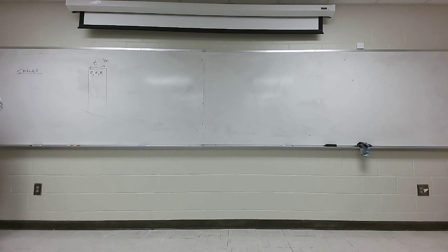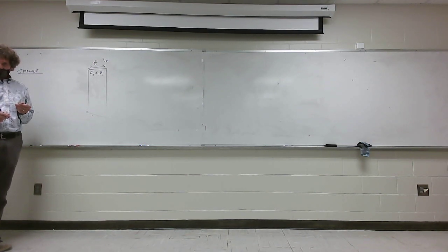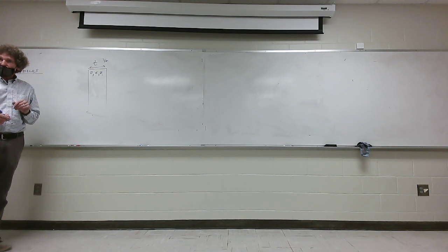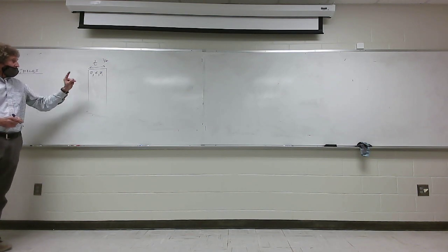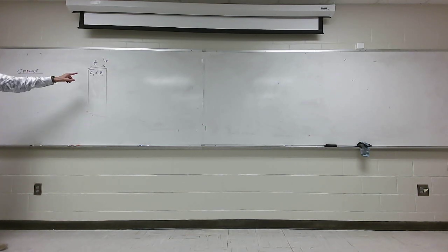Now, in the past, you usually assume mu is just mu 0 and mu relative is 1. It's not true for shield. For steel, for instance, 1045 steel that's used everywhere, mu relative at the frequencies of interest for shielding is about 1,000. Now the conductivity is a little less than iron, or in copper, but that mu relative becomes important. Epsilon relative equals 1 for almost all shields made of conductors. So you don't have to worry about epsilon relative, but you have to keep an eye on mu.